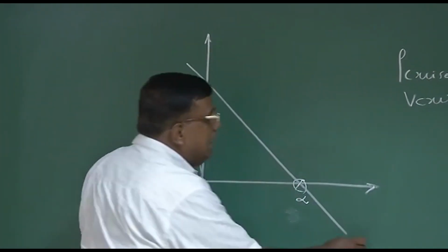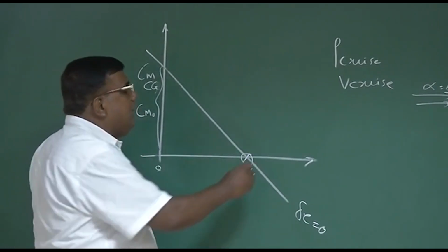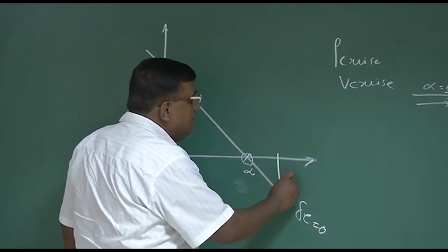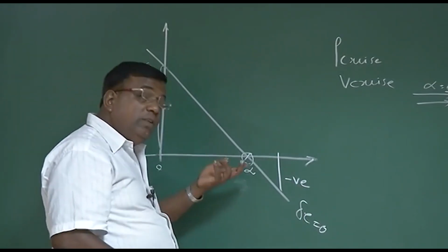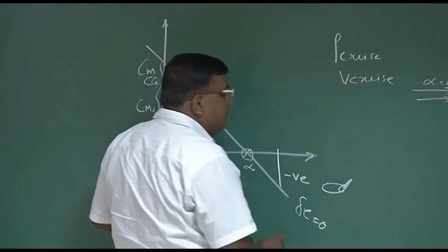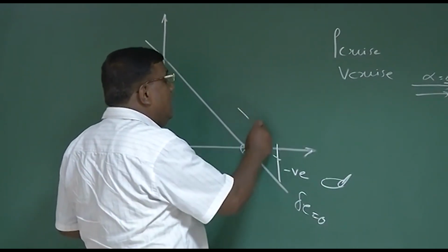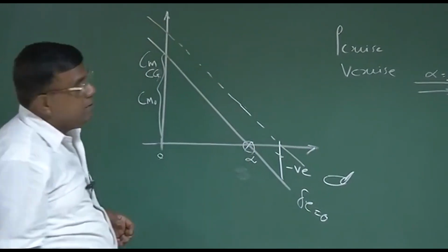Now this is delta E is 0. Now for some time you want to fly at a different alpha with different CL. Then what does it mean? It means it will generate a negative moment. So you have to now use the elevator in an up condition, so that it gives a positive moment about CG, and this gets nullified, and your Cm versus CL graph becomes this.